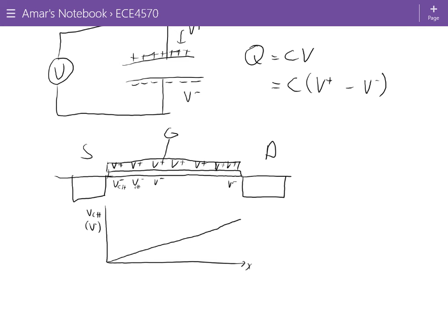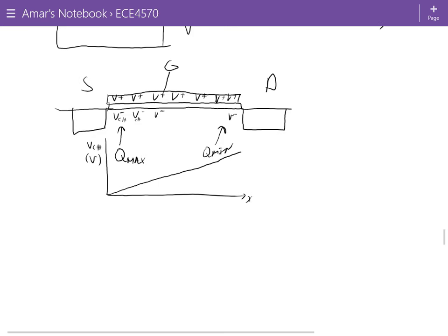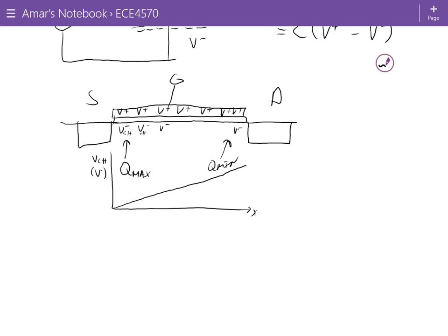So the V plus is constant for all parts of the channel. V minus is increasing as we go from left to right. So the source side is going to have the most charge. We call this Q max. The maximum amount of charge is on this side. The minimum amount of charge is on this side. So if I were to say this another way, if we were to plot Q...